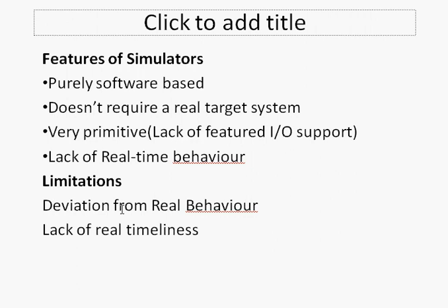To some extent, if you want to run the same program given in your lab, the same program may not work sometimes. You may have to change the delay so that it will give you the correct answer. So if you try a stepper motor program or DC motor program in the Proteus platform, then definitely you will come to know what deviation from real behavior means. So delay and all you have to tune a bit.